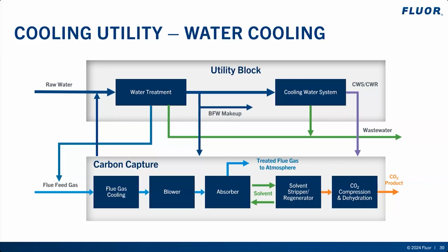Projects must consider raw water availability, additional infrastructure to deliver the water to site, and additional water treatment requirements subject to the source of the water quality. Similarly, blowdown rates can also be significant, impacting facility disposal water considerations and associated disposal water infrastructure.